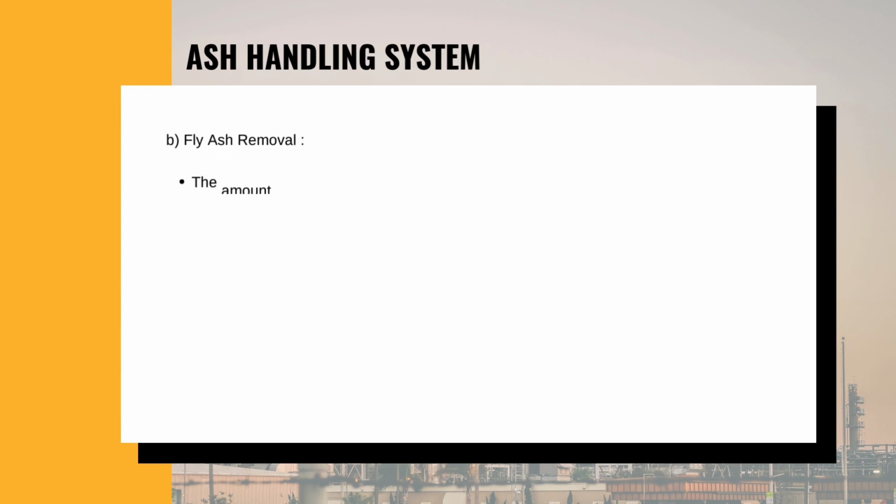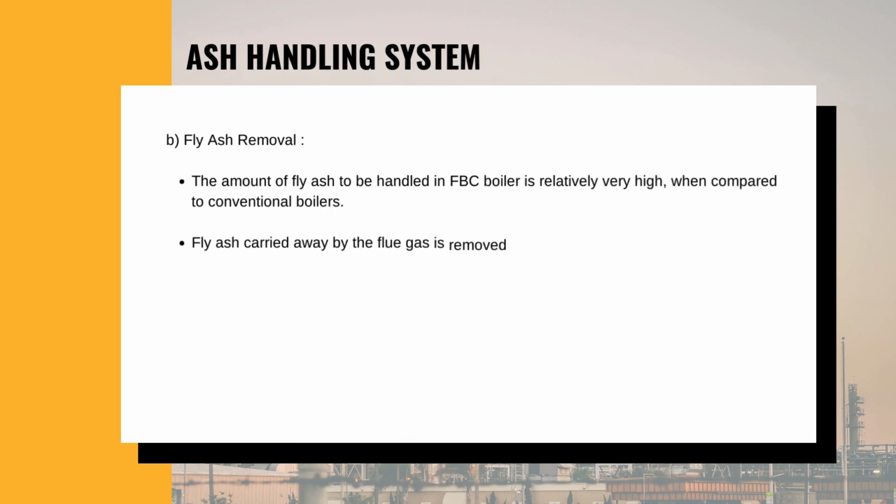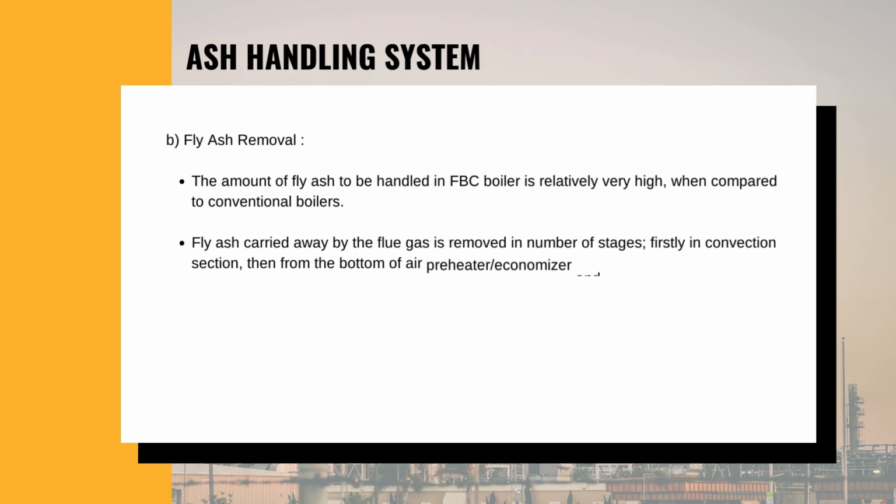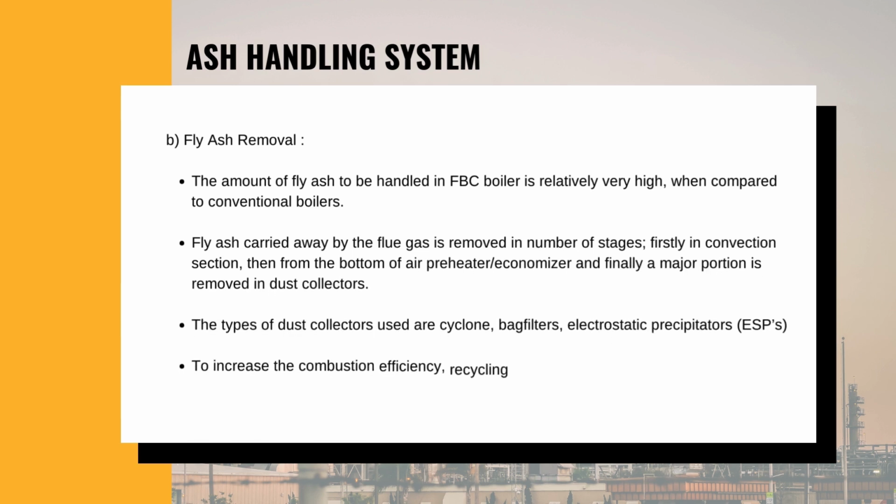Fly ash removal. The amount of fly ash to be handled in an FBC boiler is relatively very high when compared to conventional boilers. This is due to elutriation of particles at high velocities.